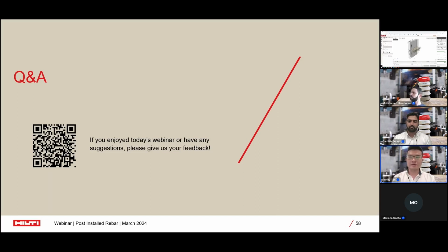When you select one of the European countries, ensure that the design method, instead of having AS 5216 plus AS 3600 or the AFAC notes, you can simply change to the Eurocodes section. So EN 1992, part 1 or part 4.